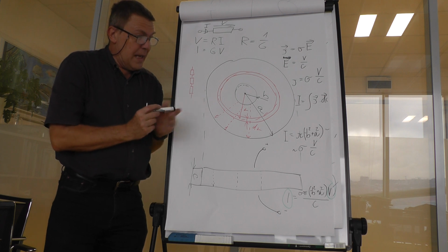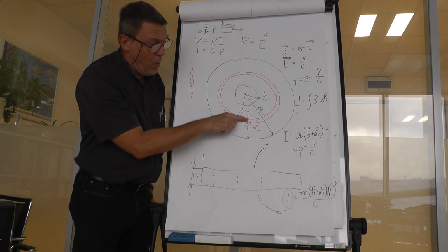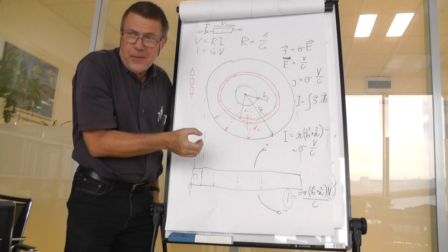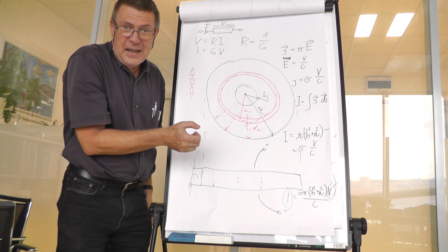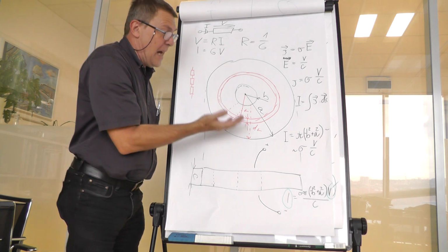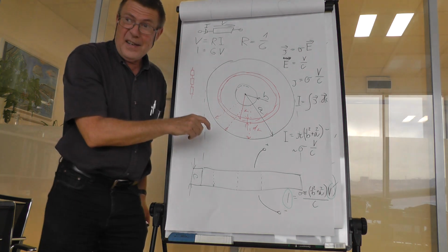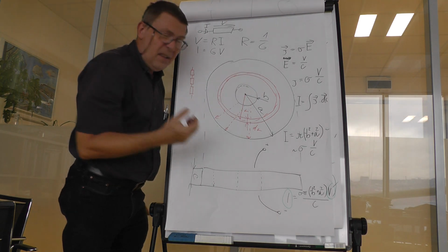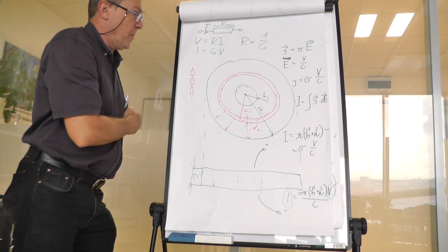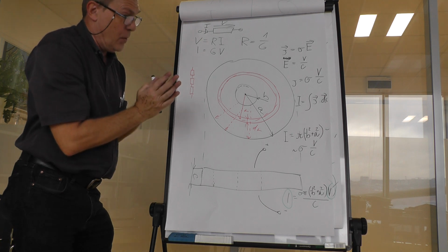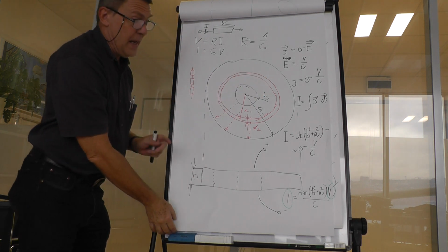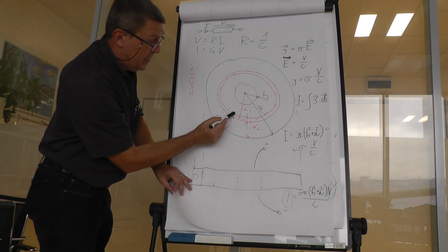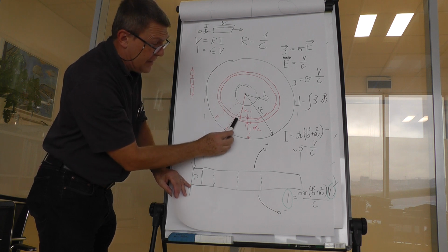But the trick of integral calculus is that we take a very small element where those two radii differ only by a differential piece, and the differential piece is, as a limit process, of no thickness, so that the value of current density here and here is the same, and also the field strength is the same within this small differential onion skin layer. And therefore, we can find out the value of this differential resistor because it's so tiny that the field within it is homogeneous. What would be the resistance of only this small layer?